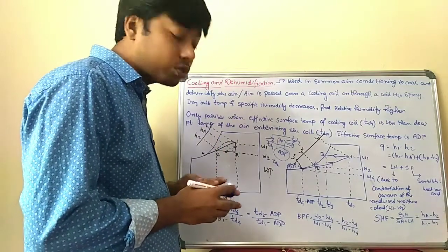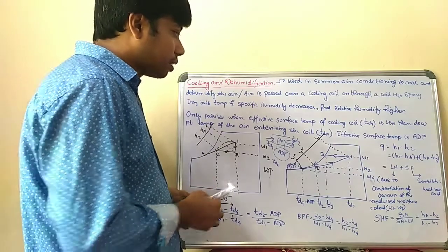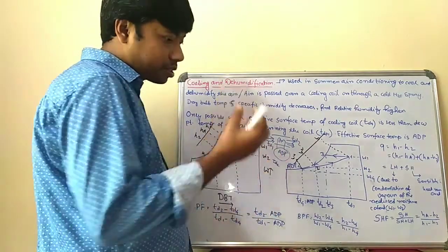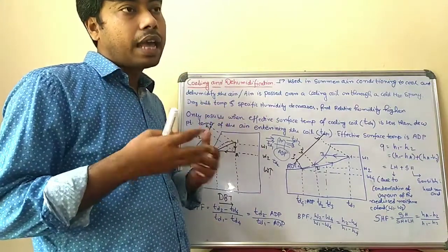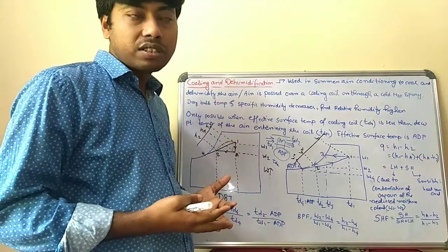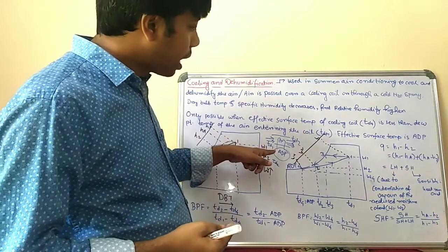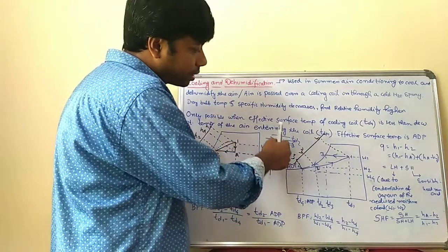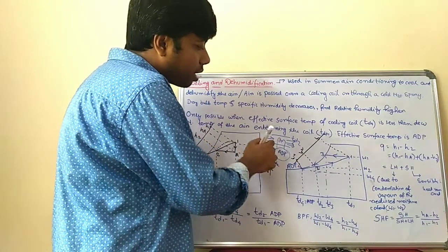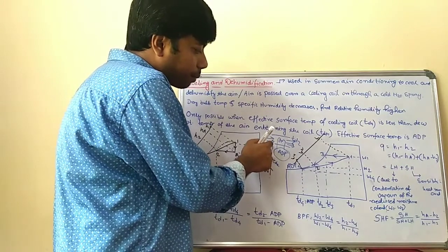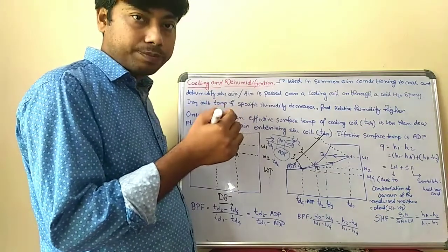But what is the method for dehumidification? For the dehumidification process, the air should contain some amount of moisture. When the air contacts the cooling coil, whose temperature is the apparatus dew point temperature, first you have to measure the dew point temperature of the entering air condition.